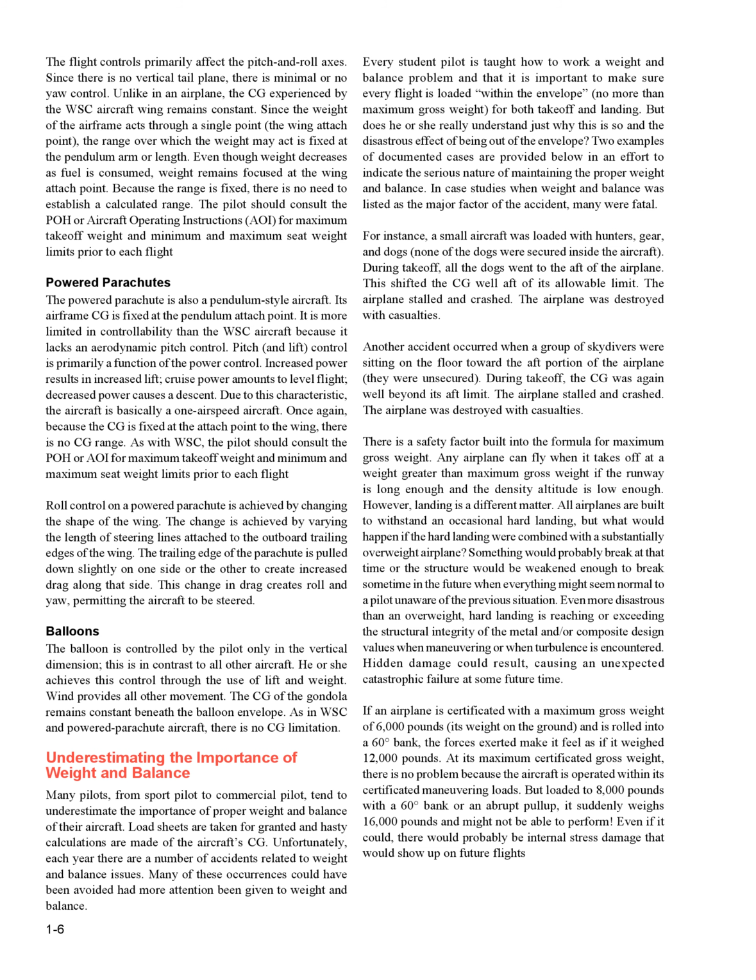The pilot should consult the POH or Aircraft Operating Instructions, AOI, for maximum takeoff weight and minimum and maximum seat weight limits prior to each flight. Powered parachutes. The powered parachute is also a pendulum-style aircraft.